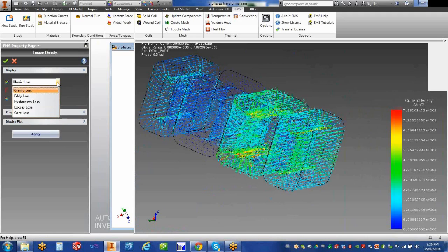So these temperatures are not coming from nothing; they always come from the losses. So if I want to change the temperature profile, I have to be able to either increase the losses if I want more heat, or manage to decrease losses by using different material or avoiding sharp corners. So different techniques to do that.